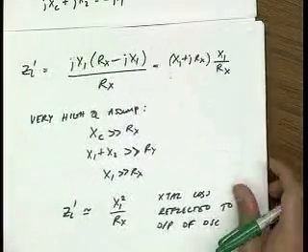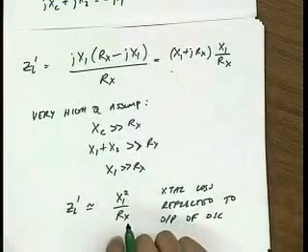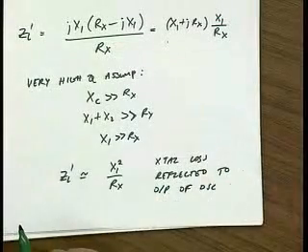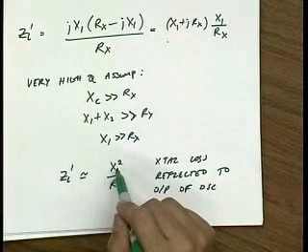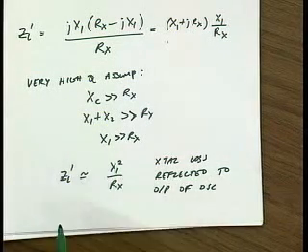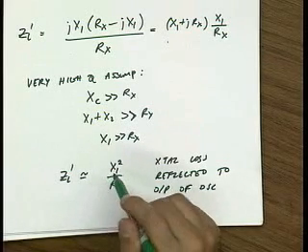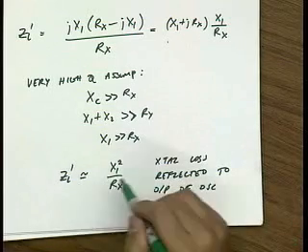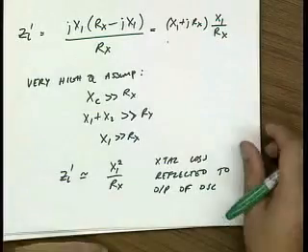Now it's interesting to look at what this means about the overtones. As we go to higher frequencies, so if I look at the third overtone, that means X_1 is smaller, right? And that means that the effective resistance is much smaller. So the shunt loss, if I translate this to the output for higher overtones, I actually get less loading at the overtones.